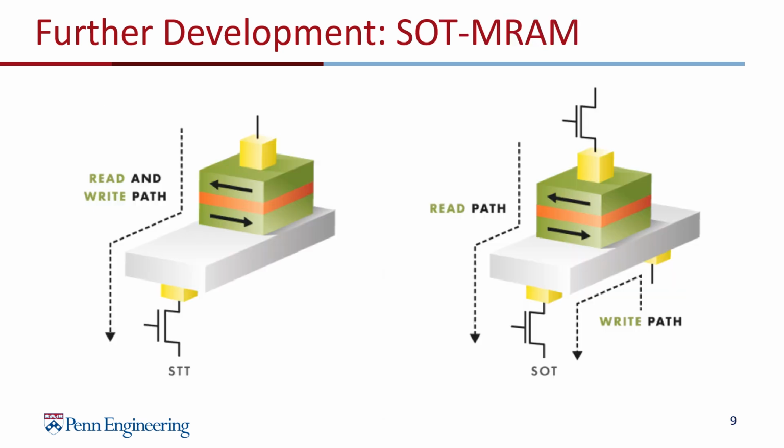Continuing the discussion of the future of STT-MRAM, spin-orbit torque MRAM is a similar technology which could challenge STT-MRAM. SOT-MRAM works in the same way as STT-MRAM, but uses an in-plane current in an adjacent layer to write to the device, and the reading process is the same. SOT-MRAM is a newer device, and so research is still being done by companies like TSMC and others, and SOT-MRAM is said to have the potential to be faster, denser, and more efficient than STT-MRAM.